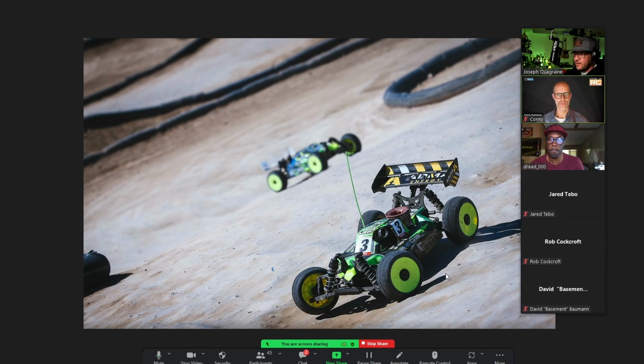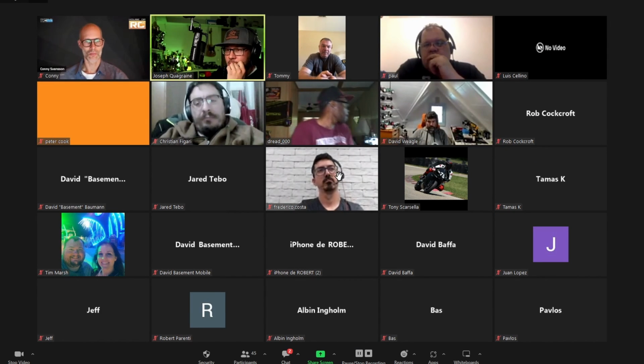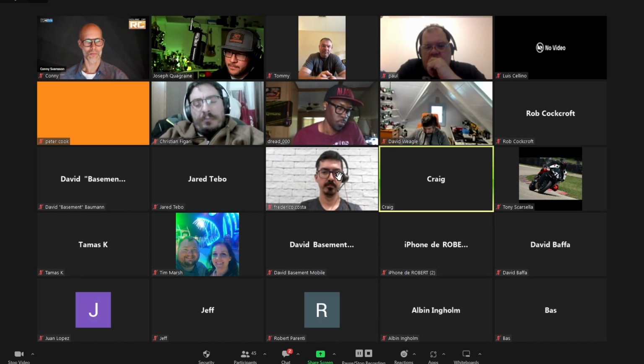If we have a car with very stiff suspension or no suspension at all, load transfers off some tires onto other tires very quickly, almost instantly. When we have suspension, if we make the suspension soft and we allow the car to roll a lot, pitch a lot, we are delaying that load transfer. So the load transfer will happen more slowly. So now we need to introduce a new concept. And the reason is that when we talk about grip.